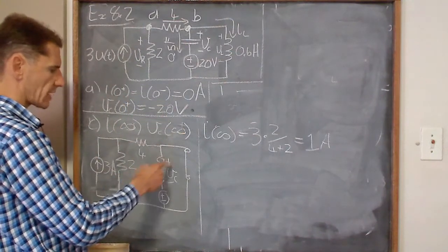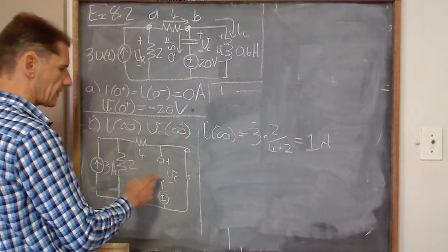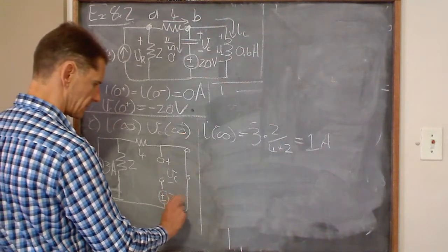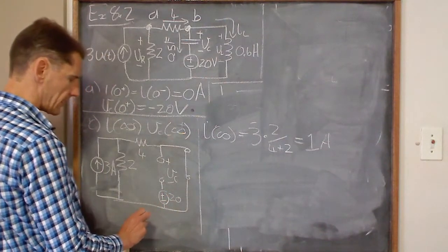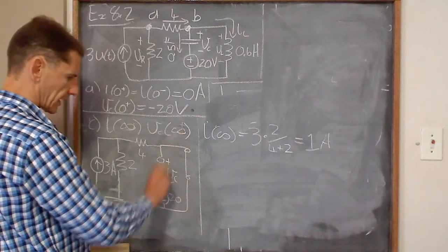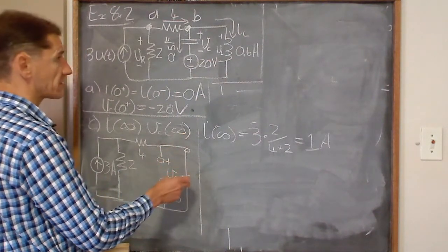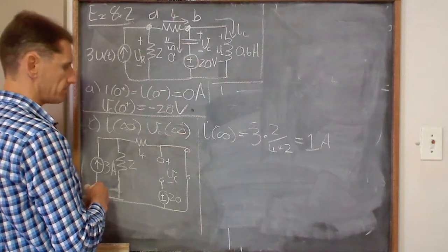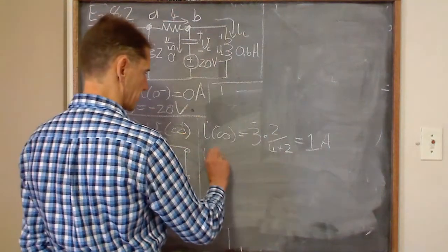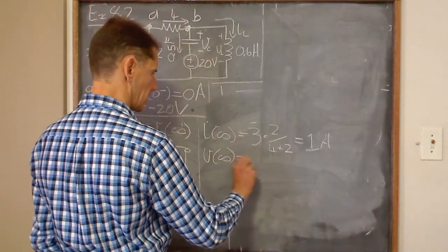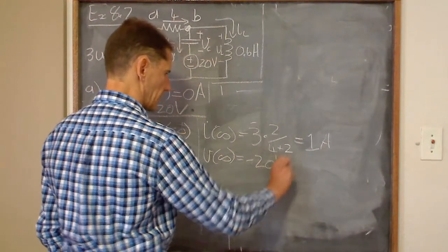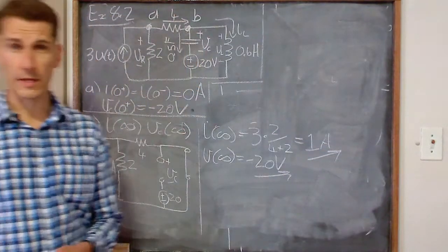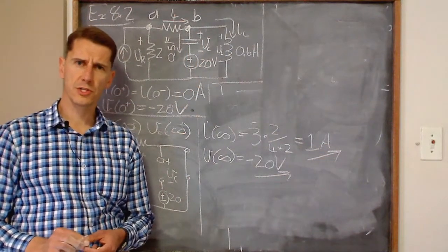Well, this capacitor will charge up, it becomes an open circuit, and then we do a KVL in this loop again, so that, remember, that's 20 sitting over there. The KVL still has to hold in this circuit, so it's pretty much the same as what we had before we switched. So it becomes a minus 20 again. V infinity equals minus 20 volts. All right, so that then sorts out this problem, or the example, in terms of the final conditions as well.